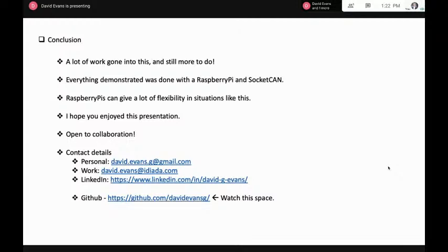Do we care if they can spoof the message? Definitely. So I think there's a lot of stuff in the works that is being enabled by faster CAN bus speeds with CAN-FD and automotive Ethernet and standard Ethernet making its way into the car, where you will start seeing maybe not full encryption, but definitely message authentication, and possibly even encryption. There are a lot of different ways you can do that, but at minimum message authentication to make it a lot harder to spoof messages on the CAN bus and just pretend you're an ECU.